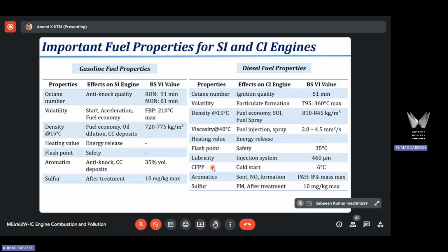Yes. So how much cost difference will it give? If we compare a fuel for a colder region and another fuel for a higher temperature region, how much will be the cost difference? No, that's what I'm saying. It's very difficult to give the number here, because, as I said, the decision has to be made on the spot. How much additive I need to add, whether I need to add any additional engine technology, I need to take a call based on the surrounding ambient temperature. For example, in Western countries, they will definitely have a starting aid. They will definitely have a heating system. Otherwise, the engine won't start. Here in India, the northeast states will have very low temperatures. Again, ambient temperature is a variable. Based on that variable, you have to fix the additive quantity. You have to take a call on whether we need additional engine technology.